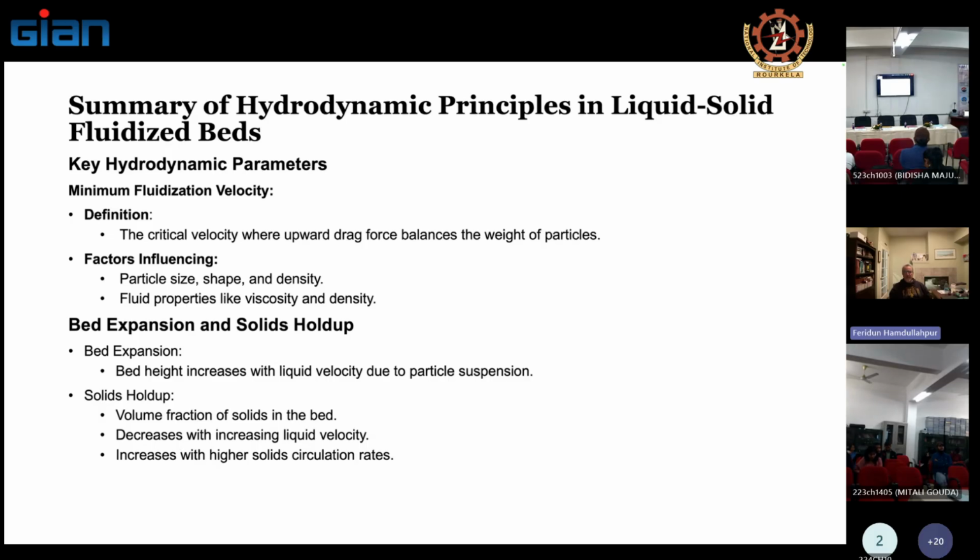In this case, if your wastewater is laden with a lot of solid particulates, and those solid particulates are also interacting with catalysts or other particulates, then you need to determine the overall bulk density and that expansion.